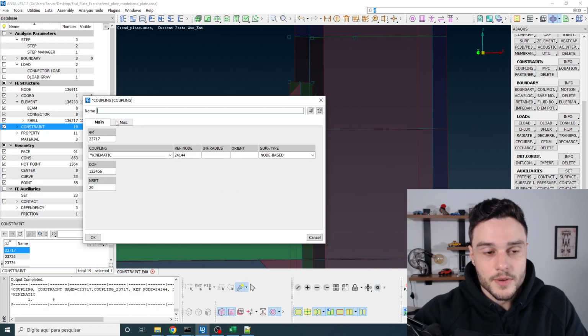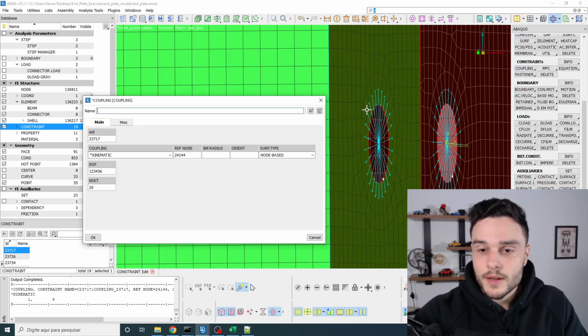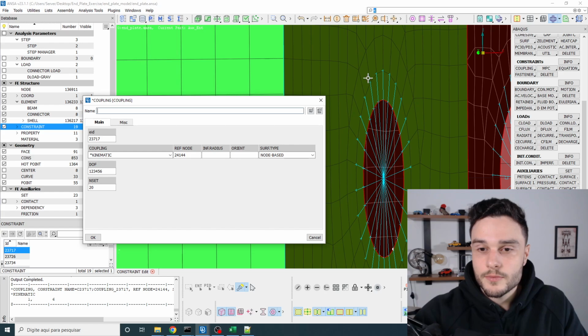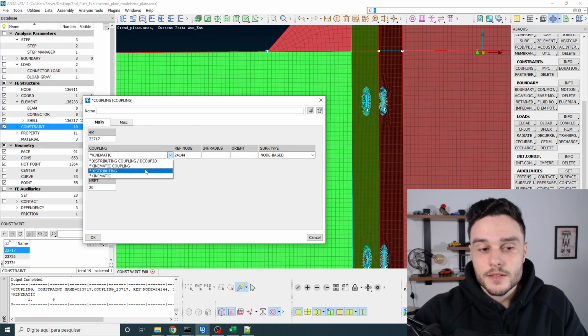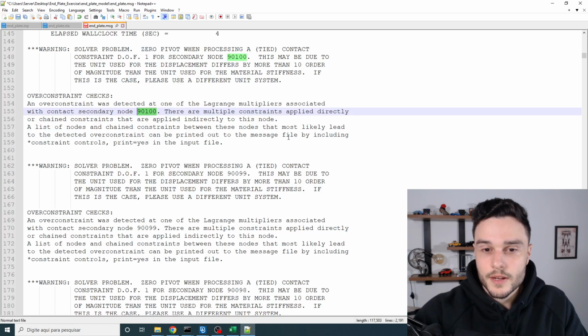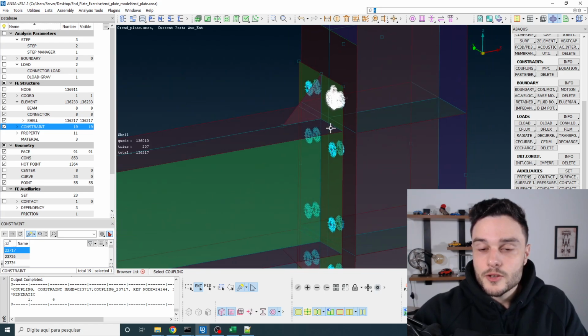double click here, and then you see that we have a kinematic coupling, which is a rigid coupling. A kinematic coupling generates constraints that make the relative position of these nodes constant. So this becomes rigid, right? So this is a constraint. Now, if we select distributing, then this coupling is not going to be considered anymore a constraint that has Lagrange multipliers.